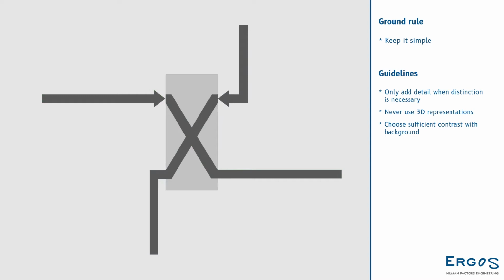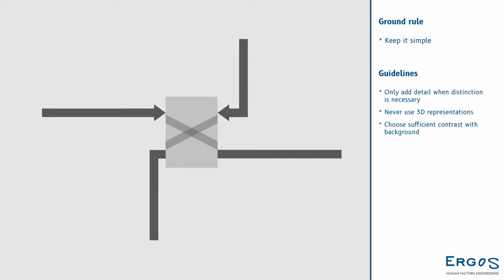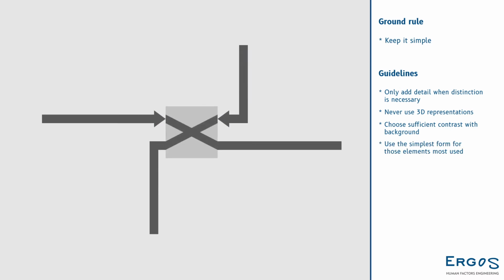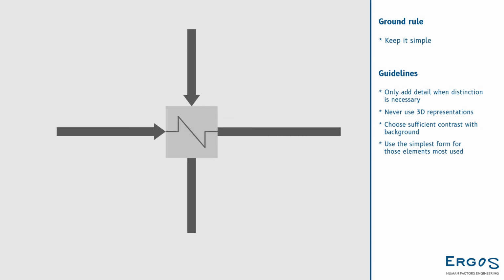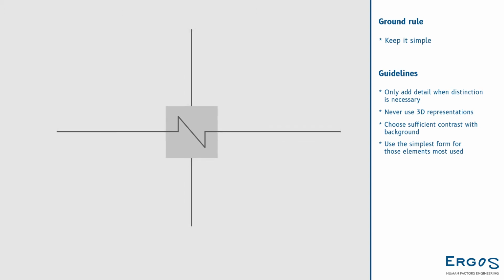We use a basic square shape as opposed to round shapes which are used for motorized symbols such as pumps. This same basic square shape can also be used for a filter symbol and other static objects. To indicate that this basic shape is exchanging heat, we use the commonly used heat exchange symbol. This new simple representation also complies to the guidelines we discussed in our first video about pipelines.